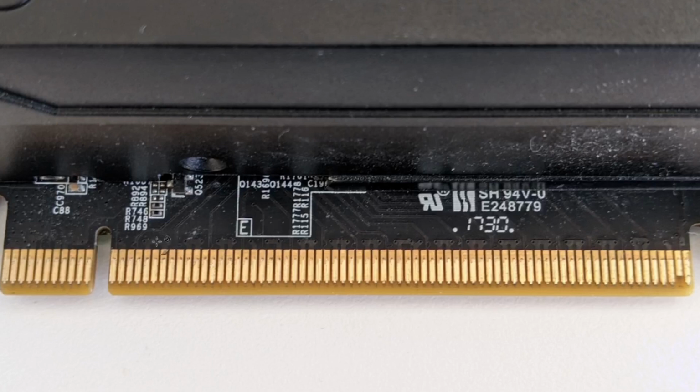Each of 2 traces here forms a set of differential pairs for each PCIe lane. And you can see here on the board, these traces are actually visible, and each of these has a set of 2 that we can see clearly on the board. This allows the card to run in 1, 2, 4, 8, and 16 mode in conventional lane ordering. Now, suppose this card is dead, we will have a dead first lane here, which means that the card cannot initialize from the conventional ordering because lane 0 is used for all speeds and it cannot be used here.